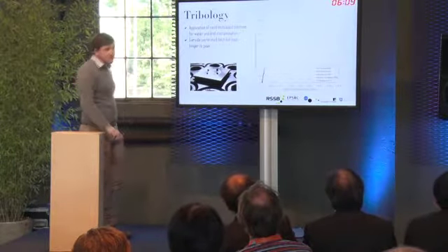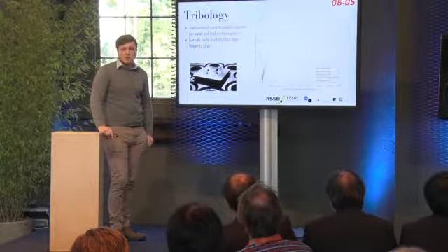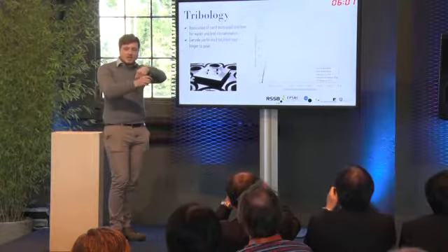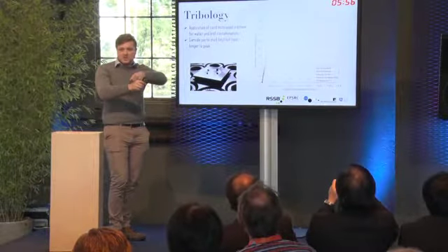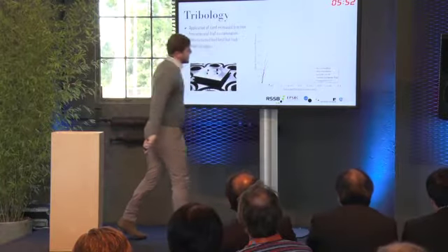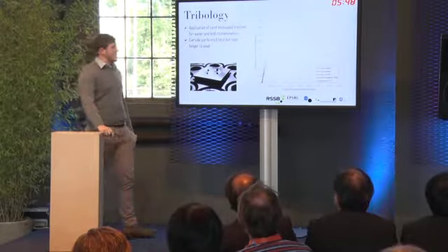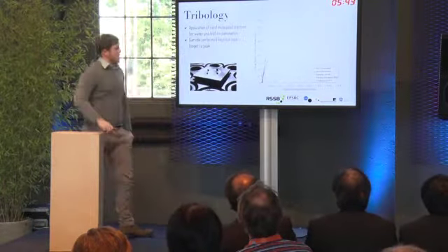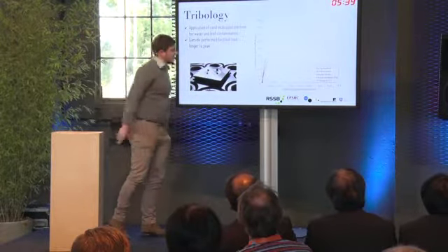So, lastly, to go on to the tribology of it all. I used a high-pressure torsion machine to look at these. Essentially, you apply 900 megapascals of pressure and then twist until you get some sort of dislocation through a set motion, in this case 0.4 millimeters of displacement. I looked at this with a dry contact here, which produced a very high coefficient of traction, which you see here.